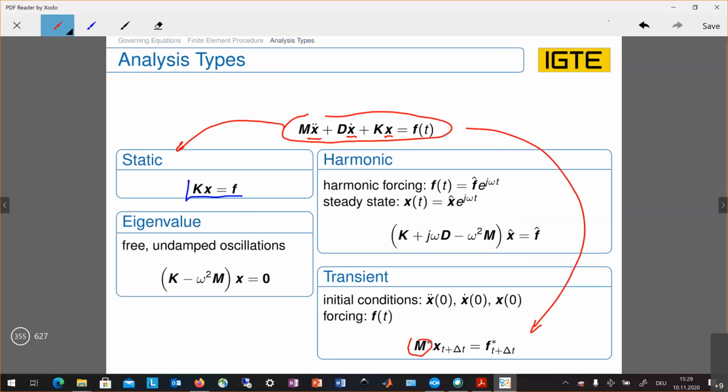We will discuss how we do the time discretization, but it will be very similar to what we have discussed for the heat equation. The difference clearly is that we have a second time derivative here, and for the heat equation we just have a first order time derivative. With such a transient analysis, we then also have to discretize this semi-discrete Galerkin formulation in time and compute our solution for each time step of interest.